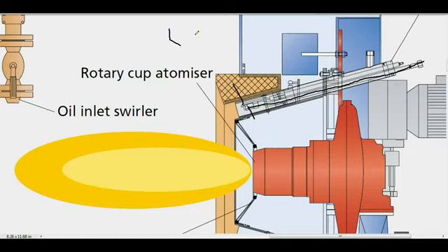It will be somewhat like this, arranged like this, and you have to always measure the clearance between these two. It will be stated in the manual. In my last ship it was approximately 3 mm, roughly of this value. You have to refer to the manual and adjust it accordingly.